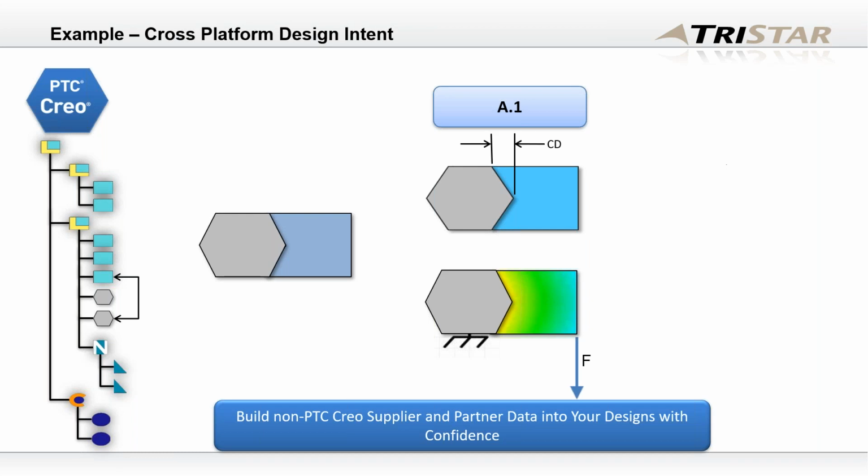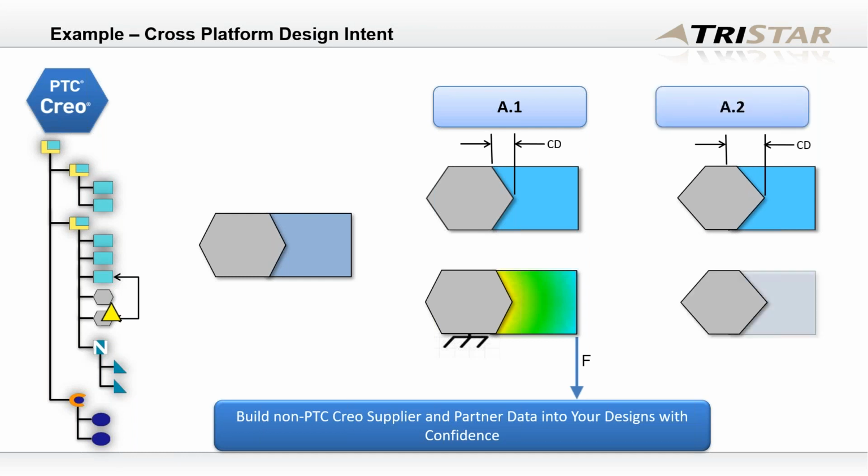I'm doing an analysis where I have an assembly in the multi-CAD format, wherein I may have some parts in Creo, some parts in the SolidWorks format. But if they make a change to the original file, I'm able to use a collaboration extension and have it update. There could be some geometry that's dependent on that other geometry. I may have done some flexible modeling edits or FMX edits or geometry edits that would update.